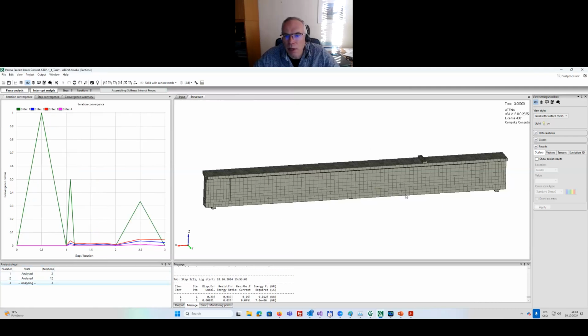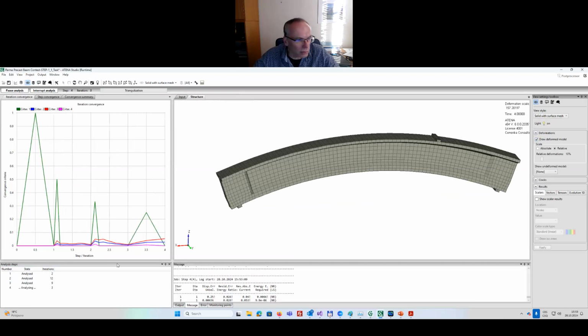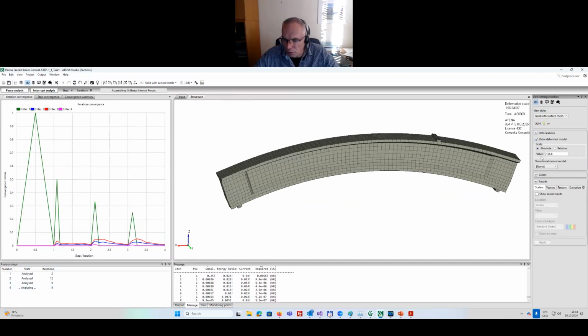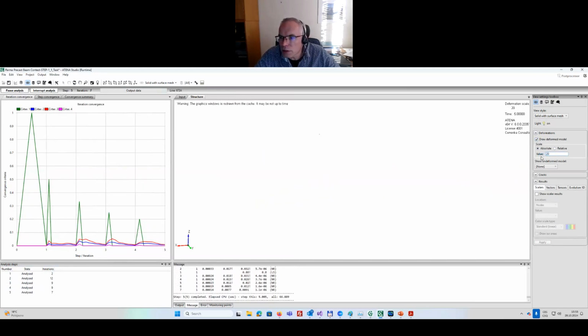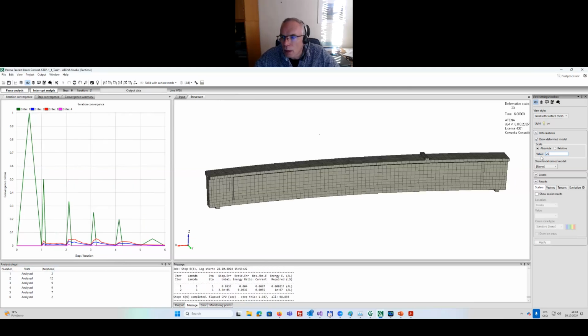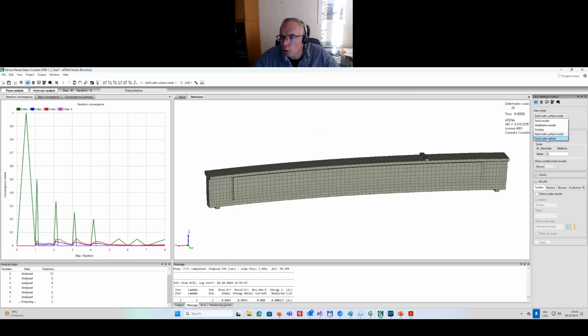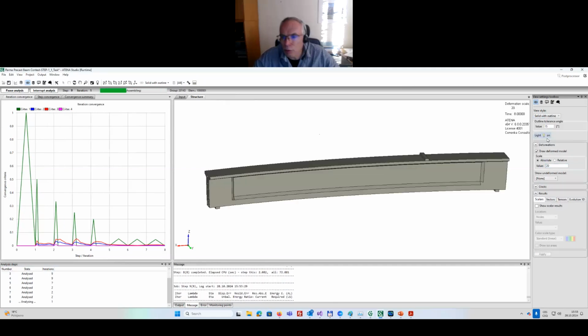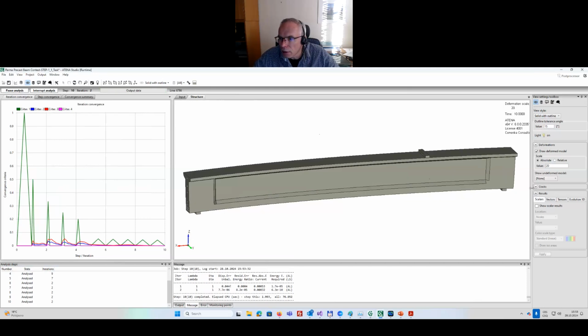Now we are in the 3rd step. Here we can display the deformed shape of our structure. You see that we are in the first 5 steps applying the pre-stressing, so the beam is bending upwards, but I will reduce the deformation scale a little. I usually like to display it with solid outline, because later it will be nicer for the visualization of the cracks.